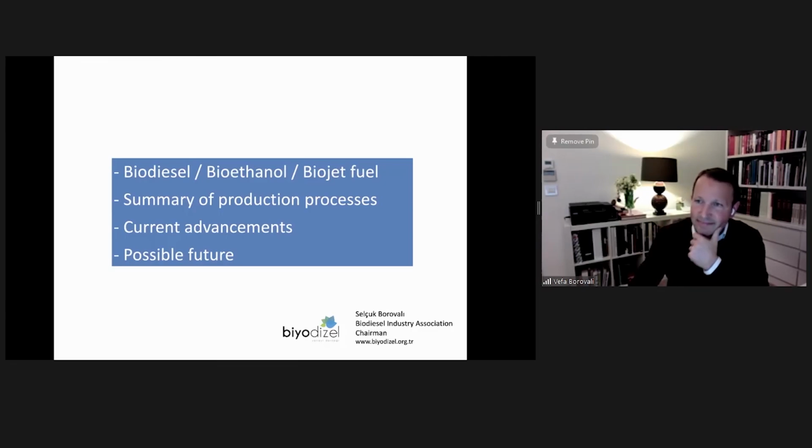Okay, and the last question is, why do industries use batch reactors for transesterification reactions? Well, batch reactors are always easier to use, especially during the first stages of becoming familiar with the process. Batch reactors are the safest in terms of controlling the reaction. You can play with the duration of your reaction. You can play with the amounts of reactants. You have more control on a batch reactor. And of course, the other good part is that in case you fail in a batch reactor, you might find some ways to recover the feedstock, the raw material you used in the tank, and you can start again and try to reach the end product.